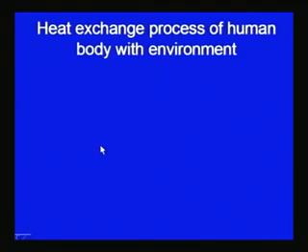So, here we can see the air temperature and wall temperature significantly affect the way by which heat loss to the environment takes place by the different modes of heat transfer. For too high air and wall temperature, the heat loss mainly takes place by evaporation, while for low temperature conditions, it is the combination of all three, where convection dominates and evaporation is the minimum one.